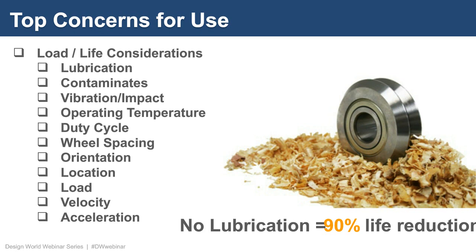You also might be concerned about the types of contaminants and the amount of it. Light sawdusts are very soft and can be pushed out of the way easily, so those aren't much of a concern. But you might have maybe ceramic tile dust, which is very hard, and it might be in a slurry, and so that could be very abrasive. You might have to worry about that a little bit more. Vibrations and impacts are also not a good situation for guide wheels. You can make small dents which do not spring back, and any dents or deformation of the steel could lead to a longer-term problem.